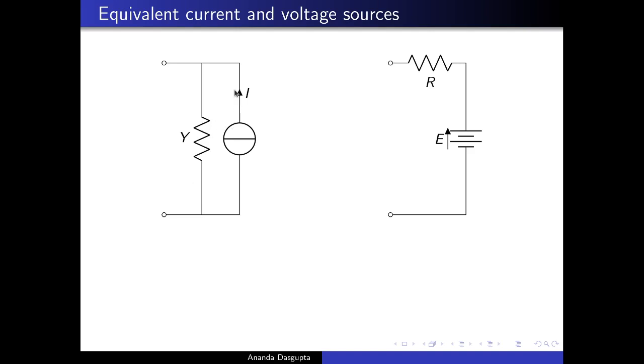Now what does this really do? It essentially does this. If you have a very small resistance connected here, almost all of the current will go through the external resistance. So the entire current delivered by the ideal source, almost in its entirety, will flow to the external circuit.